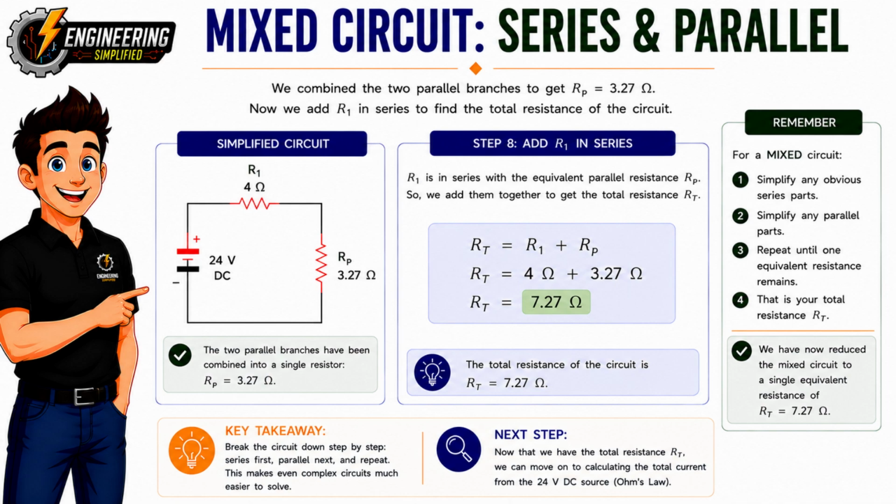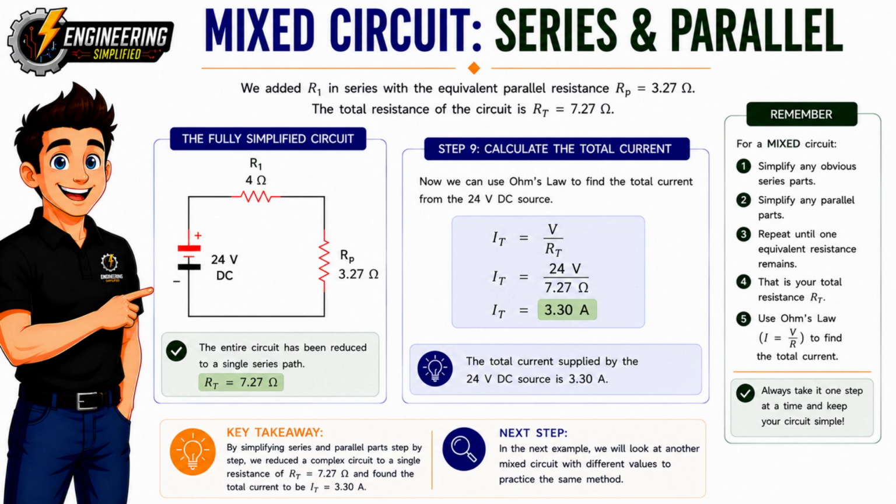Now that we know the total resistance, we're ready to use Ohm's law to calculate the total current supplied by the source in the next step. We've now simplified the entire mixed circuit into a single series circuit. We already know that the total resistance is 7.27 ohms. Now we can use Ohm's law to calculate the total current supplied by the 24-volt DC source.